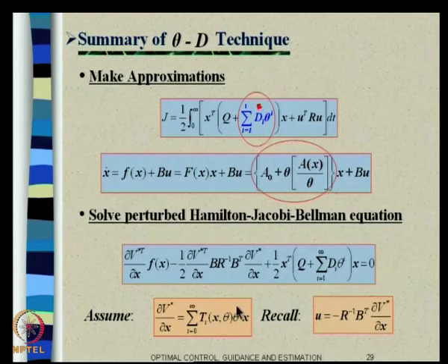We will give an example a little later when you go along, but the difference is now sometimes people take the V star as power series expansion and all. Instead of that, what is done is as the lambda or del V by del x, which is a vector, that is expanded as some sort of a matrix times some scalar times the state actually.